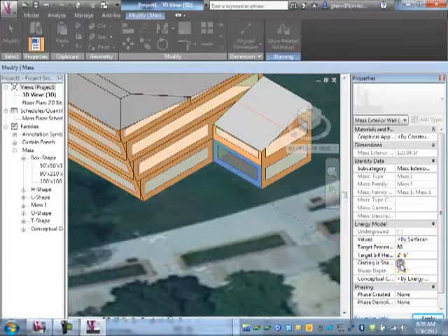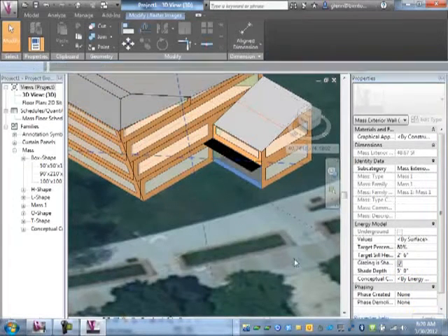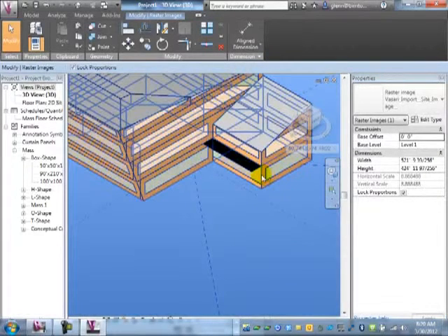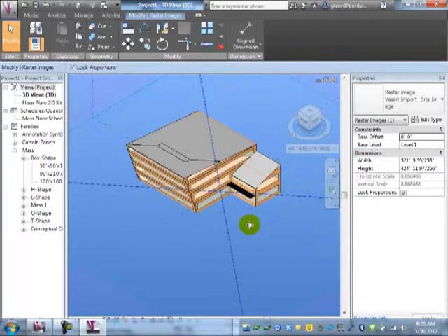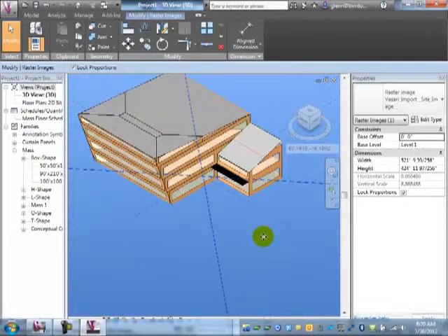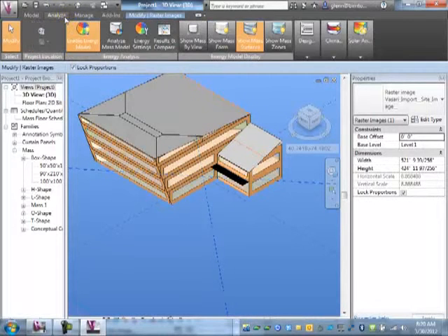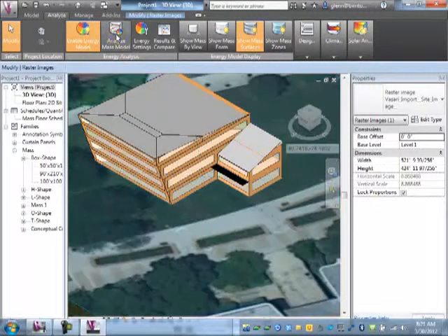And I'm going to put a shade on this surface that's going to be 5 feet out to provide some shading. So I'll get a lot of view of what's going on in the green, but I'll also have some sun shading to hopefully keep the sun from making that room too hot. Hopefully it'll warm it during the time that we do want it there. So we can start adjusting and adapting these things. But at a high level, what Vasari is good for is doing this. You can create several alternatives and compare them, but I'll do it for this one. I'll analyze this model.